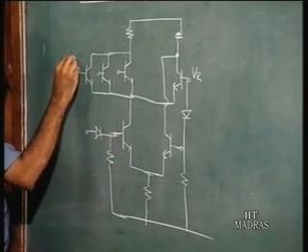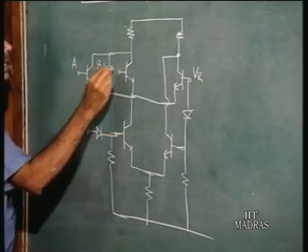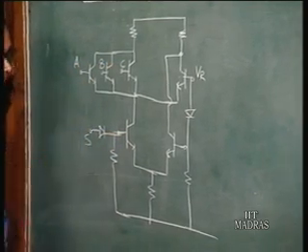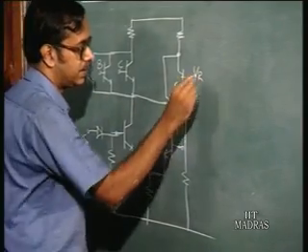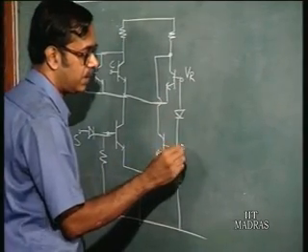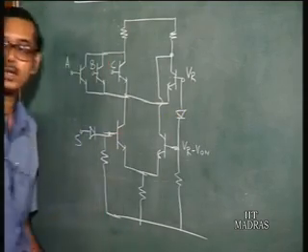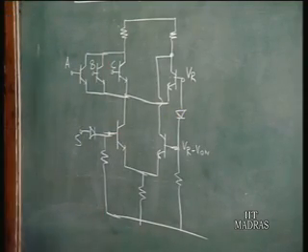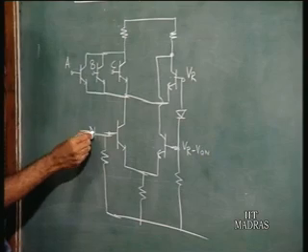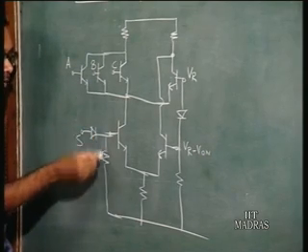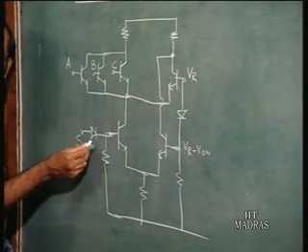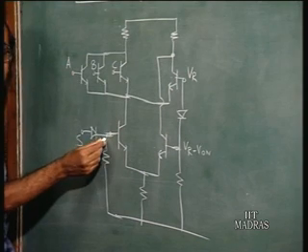So let us say you have the inputs A, B, C here. Let us say you have the input S here, and this is VR, and this basically would mean it is VR minus V on, where V on is the drop across the diode. And of course, here also the purpose of this diode resistance combination is to reduce the voltage by one diode drop.